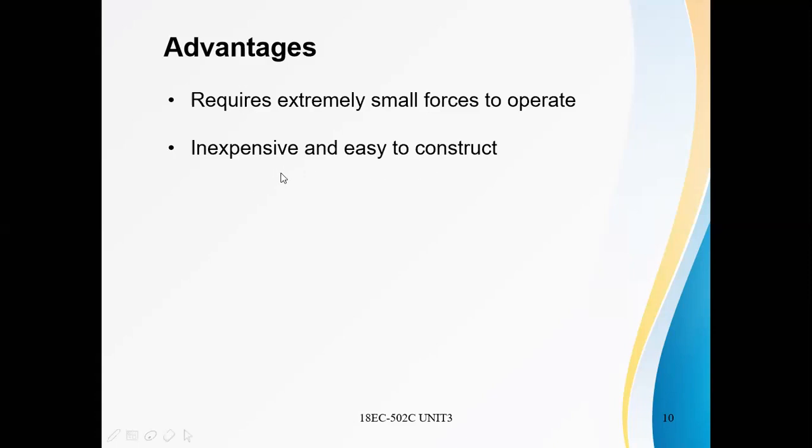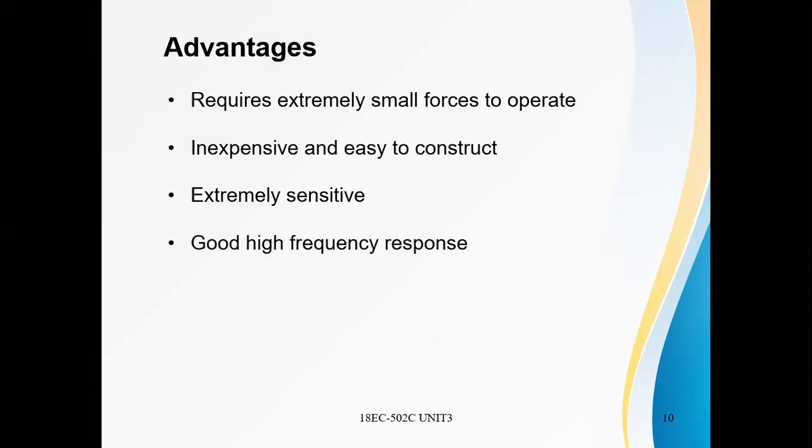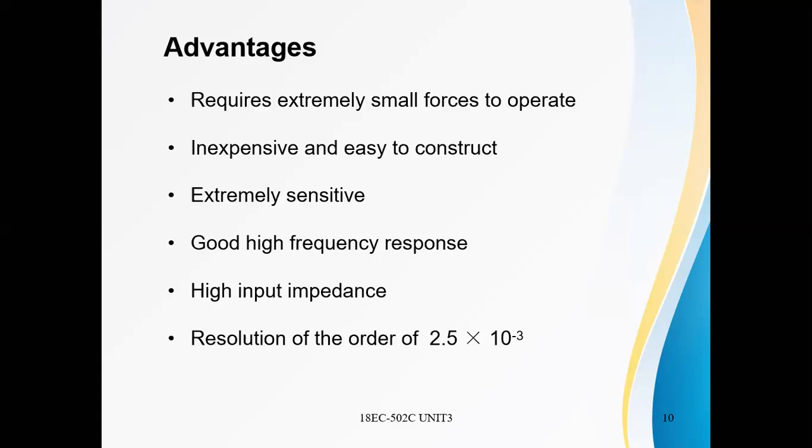Cost is also less. Extremely sensitive. It only requires small forces, so the sensitivity is also very high. Good high frequency response; the frequency response of the capacitive transducer is good. High input impedance is another advantage. And resolution: the resolution of this capacitive transducer is of the order of 2.5 into 10 power minus 3.